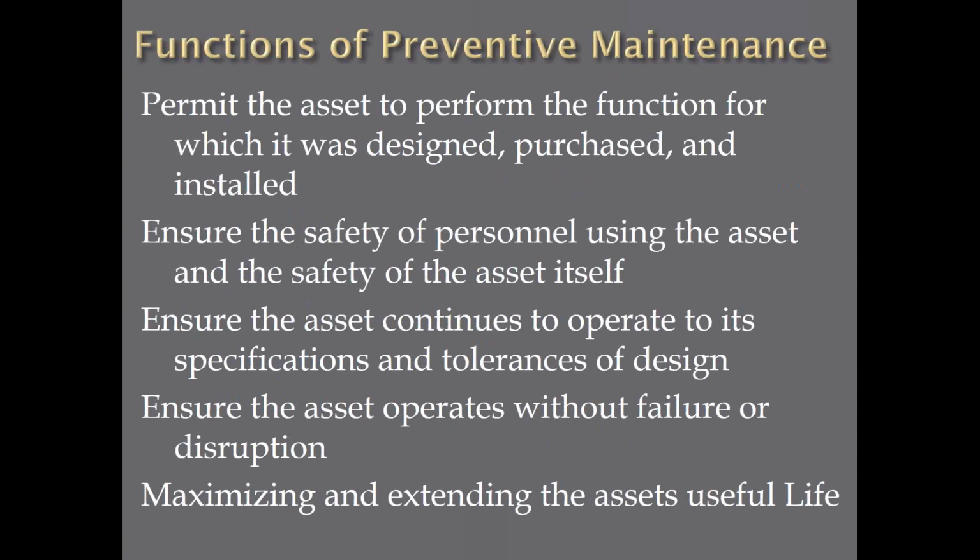And then the last one here, functions of preventive maintenance. Permit the asset to perform the function for which it was designed, purchased, and installed. Many times I go to plants, they don't even know what that is. I always ask the question, what was this machine designed to do? There was an example when a company was making wrapping crackers. The machine was designed to do 1,000 wraps per hour. They were trying to run it at 1,800. Well, the people didn't understand what that machine was designed to do.